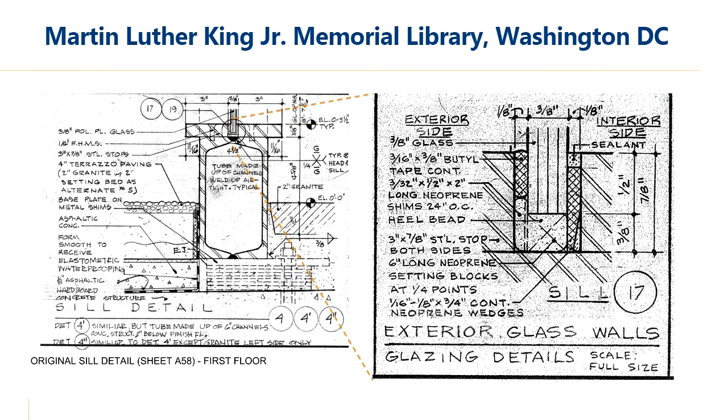So why is corrosion of the steel so important? The original curtain wall glazing support was comprised of simple steel shapes, and the glazing pocket was formed by steel bar stops secured with 1/4-inch flathead metal screws. The 3/8-inch plate glass is set into the pocket onto neoprene setting blocks and a neoprene shim separating the glass from direct metal contact. The assembly is made weather tight through the use of butyl tape at the exterior.